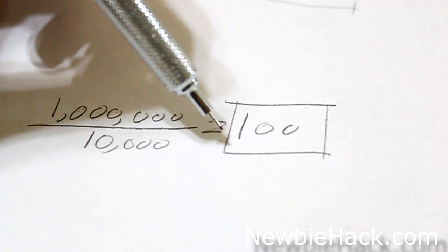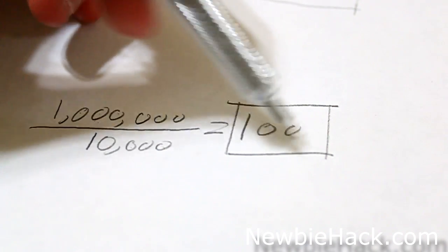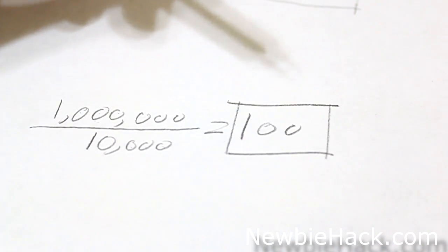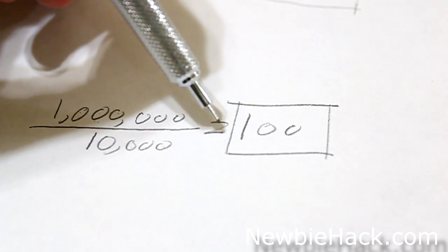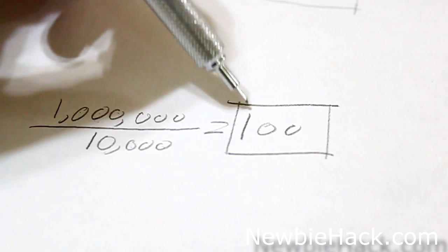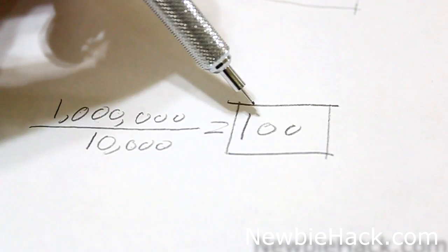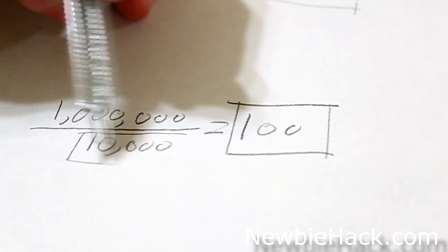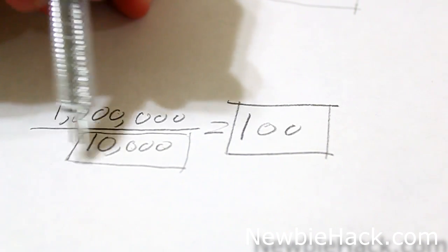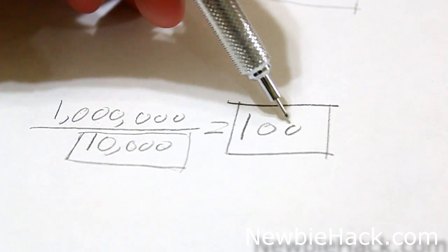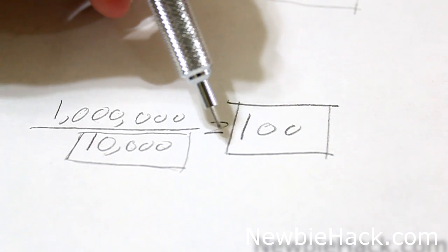and that's probably fast enough to make the LED look like it's constantly on. Because we have a pretty clean number here, 100 times per second, we could probably get down to maybe 10 times per second, or we can get down to 1 time per second, which is every 1 second, by introducing another loop. So we could say, go ahead and count to 10,000, 100 times, and then turn the LED on or off.